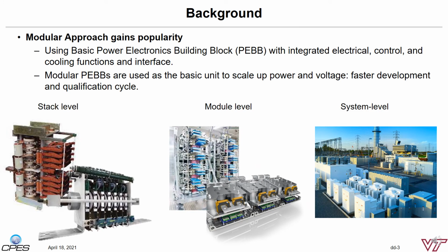So when we talk about high-frequency power electronics in high power areas, the modular approach is gaining popularity. The modular approach aligns with the concept of the power electronics building block, PEB, which is a unit with integrated electrical, control, cooling, or even filtering functions. The modular approach uses these identical modules to build up the power and voltage. This allows faster development and qualification cycles, very suitable for the recent emerging applications with very different requirements.